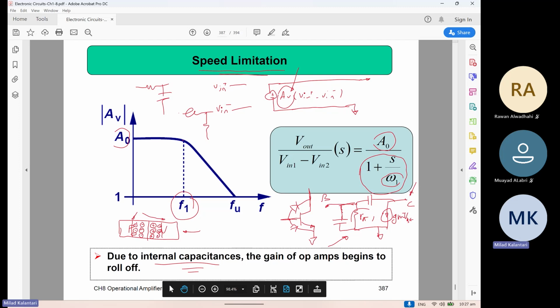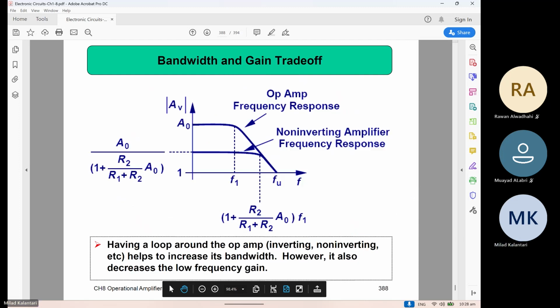So you can easily see that the device is not there. Everywhere is just shorted to each other, right? That's why the device cannot work as a good amplifier at a higher frequency, and you will see that the gain will drop after a certain frequency. But anyway, you can still use the op-amp, though it has some cutoff frequency, let's say.